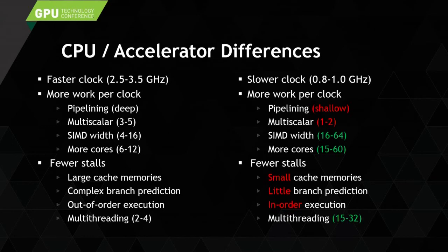A lot of branch prediction. When I get to a branch, I don't have to wait to find out which direction to go. I'll just go both directions, or I'll select a direction. And if I'm wrong, okay, I have to kill those instructions. But usually I'm right. So usually my branch prediction is good. I don't want to waste those transistors on branch prediction. I want to put those transistors into functional units. Out of order execution. This instruction has to wait for that one, but I'll just issue the next one and continue on. And that takes a lot of control unit time. There are a lot of transistors, a lot of your real estate.